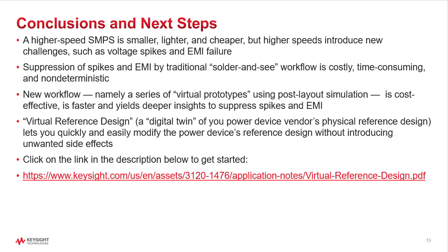You can use post-layout simulation. It's cost-effective, it's fast, and it yields deeper insights because you have the visualization to suppress the spikes and the EMI. These virtual reference designs, as I say, are a digital twin of your power device vendor's physical reference design, and let you quickly and easily modify the power device reference design without introducing unwanted side effects.